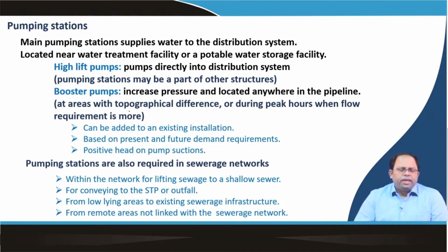So, there we need to increase the pressure, but if we design my overhead tank to take care of this extra pressure, then probably the entire thing would not be economical. So, instead I put a small boosting pumping station at this particular zone and pump the water up into the network that we designed for this particular mound. So, boosting stations are required wherever there are some terrain issues, or during peak hours when flow